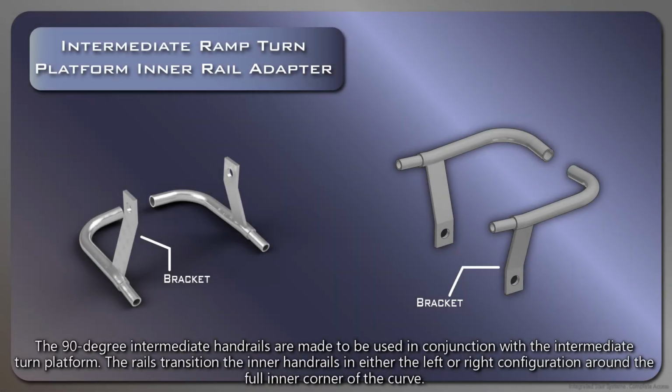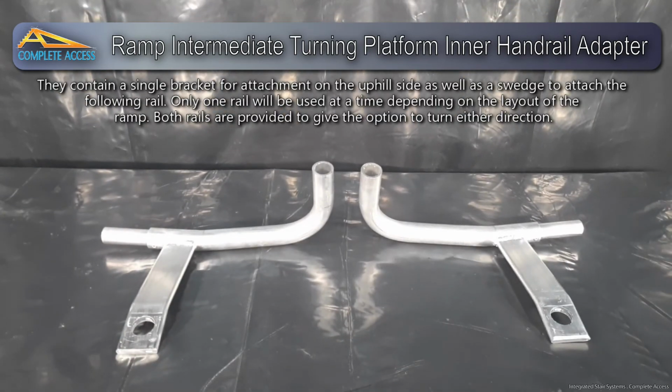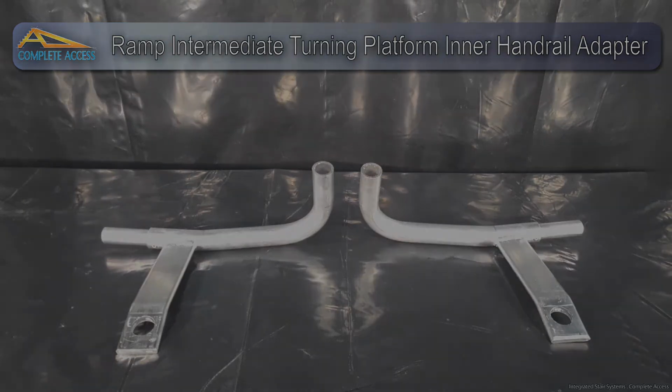The 90-degree intermediate handrails are made to be used in conjunction with the intermediate turn platform. The rails transition the inner handrails in either the left or right configuration around the full inner corner of the curve. They contain a single bracket for attachment on the uphill side as well as a swedge to attach the following rail. Only one of these rails will be used at a time depending on the layout of the ramp. Both rails are provided with the switchback kit to give the option to turn in either direction.